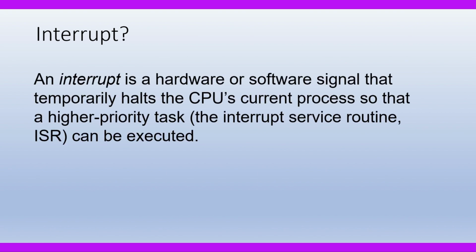Okay, what is an interrupt? An interrupt is a hardware or software signal that temporarily halts the CPU's current process so that a higher priority task, the interrupt service routine, ISR, can be executed. Let's understand the interrupt process.